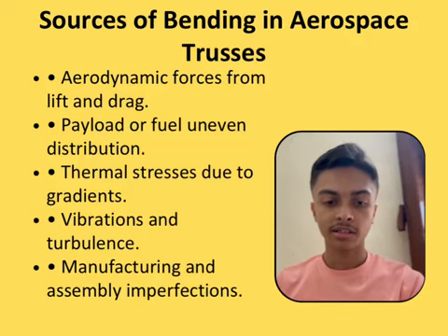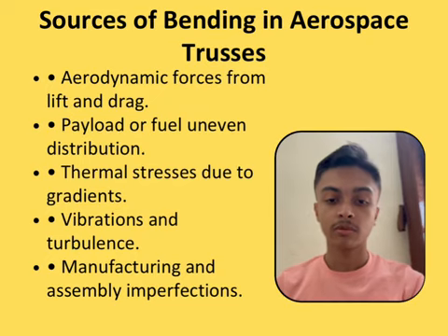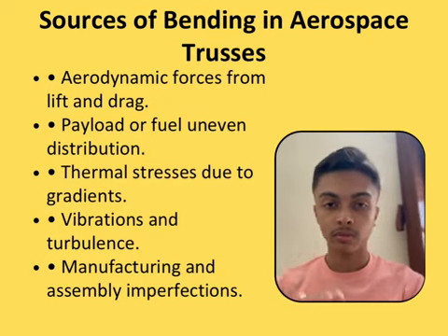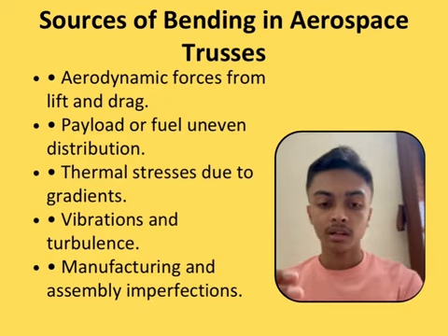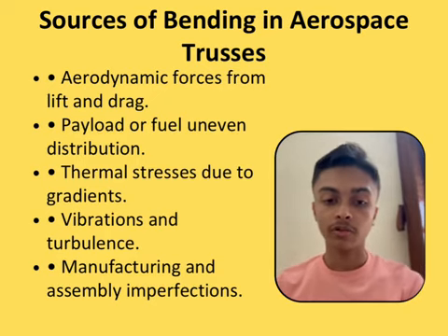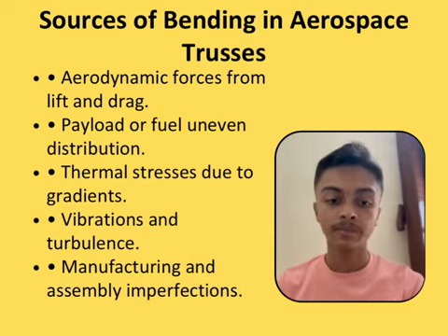Then let's discuss the sources of bending in aerospace trusses. First, aerodynamic forces from lift and drag. Then uneven distribution of payload and fuel.